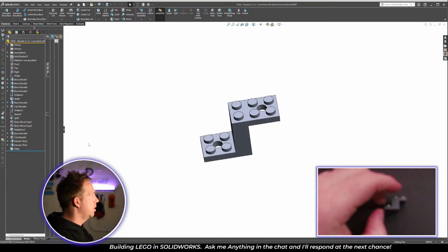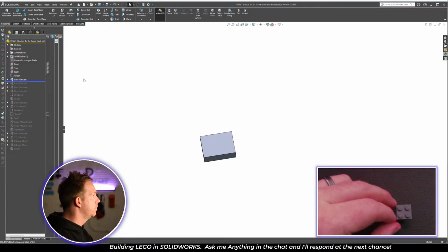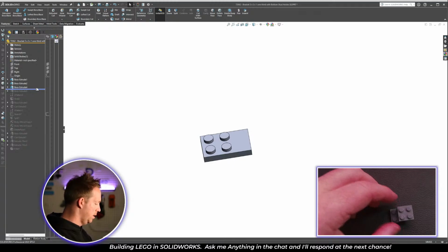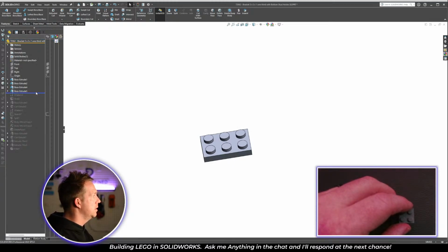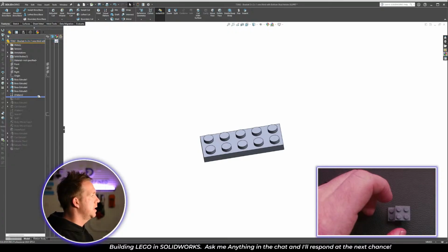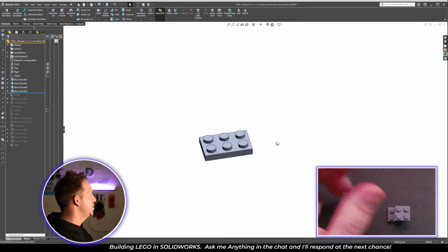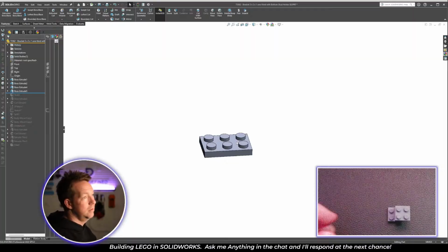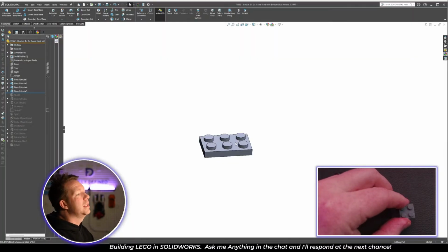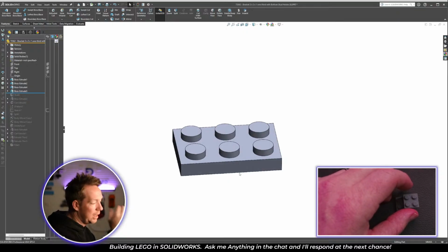And so again, we're going to roll through the tree. So the process, roll back to the start of the tree. We got details right early. Now what's different on this one is the whole thing is only three studs wide. So where I did this linear pattern last time, we don't need to do that this time. So I'm going to delete that pattern. And if you can delete a feature without it deleting other features, that's good. That saves you time. That means you don't have to go through and make a lot of adjustments.